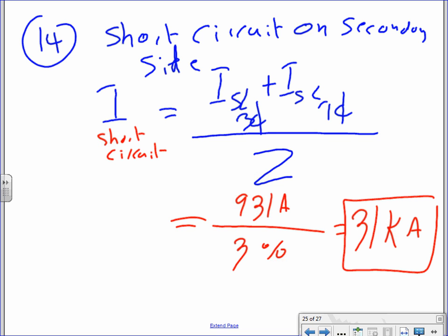Which is basically, we used the current for phase A and phase B because that's the highest, right? That's the highest line current, is phase A and phase B. Phase A and phase C. You don't add them together. Well, if you add them together, this is the one that we size for, phase A and phase C. Right? Why? Because that's a worst scenario.